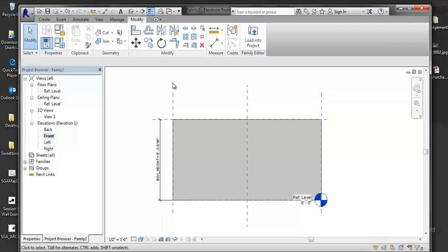And why do you think that is? It's a material and it's visible. I'm making objects visible, I'm making objects have a material. The key word in all of that is the idea of object. It's associated directly to the object. I can have multiple objects in the same family housing different sets of material parameters. So the material is not a global, it's object specific. Therefore, I need to select the object itself and assign visibility to it within that case.